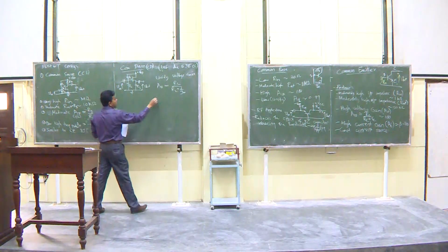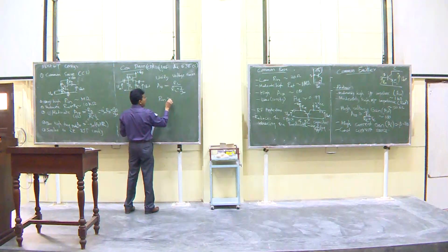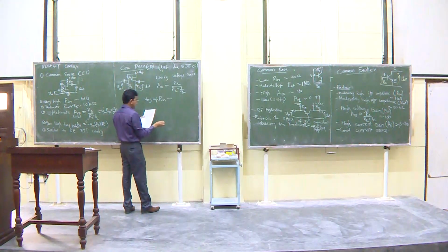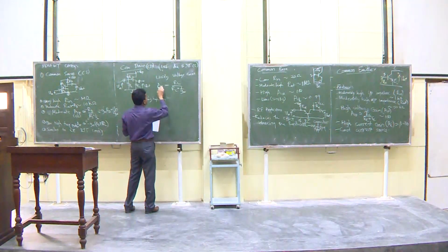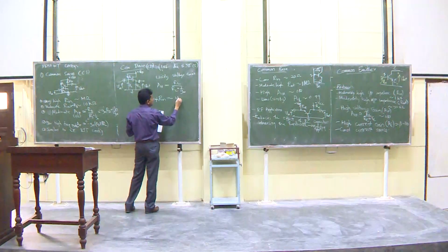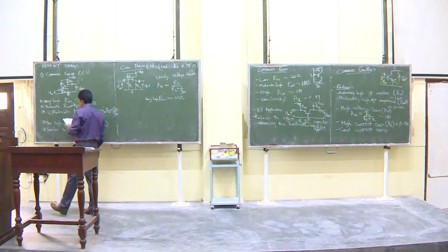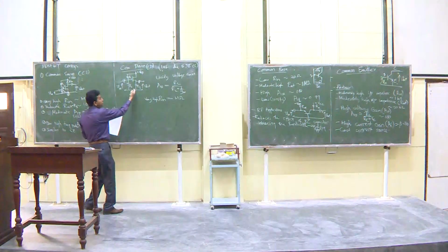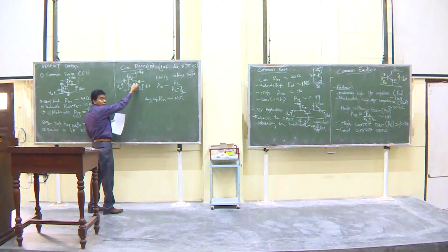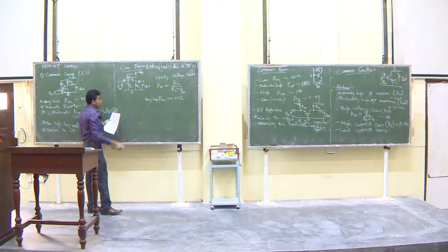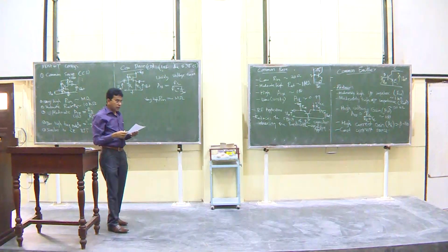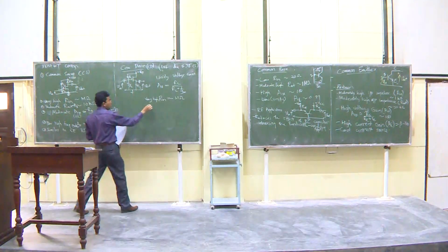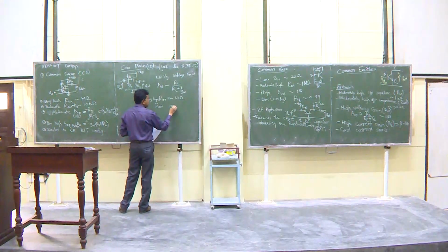Large input impedance, very high. Again, the same as the previous one, you have the oxide layer there, so this is in the range of mega ohms. What is the output impedance? It's in parallel with RS, and also there's a GM, so the parallel connection between those two will be small. So R out will be moderate.